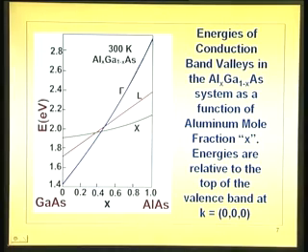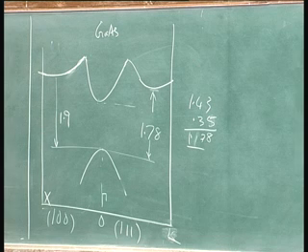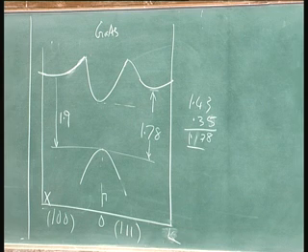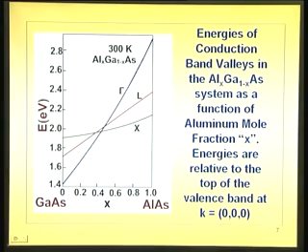It is not really straight, in fact, it will try to be straight, it latches on to the direct band gap, and if you vary x, that direct band gap keeps on varying from 1.43 to 3.02. That is what we have been telling. Earlier we were plotting this straight, strictly it is not so, it is not a perfect straight line, there is a slight curvature here.